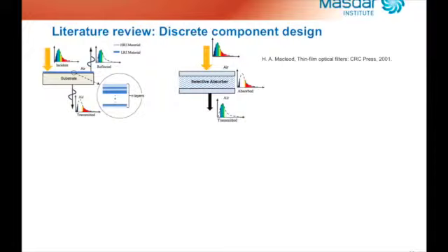As optical filter, we can use the dielectric thin film filter, which can be made of a sequence of periodic layers with different refractive index. Or as an alternative solution, we can use a Rugate filter that is basically a layer with a continuously varying refractive index structure.